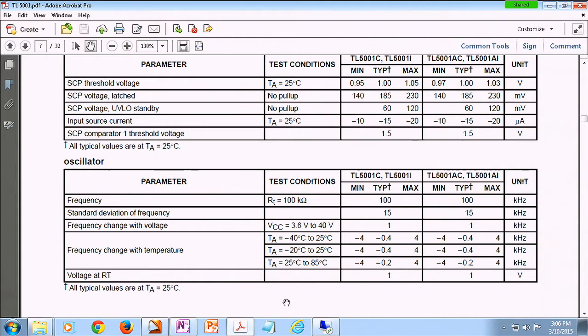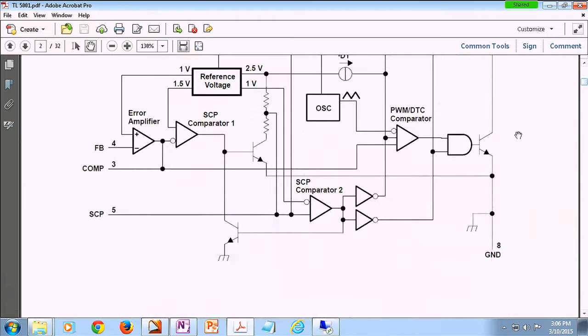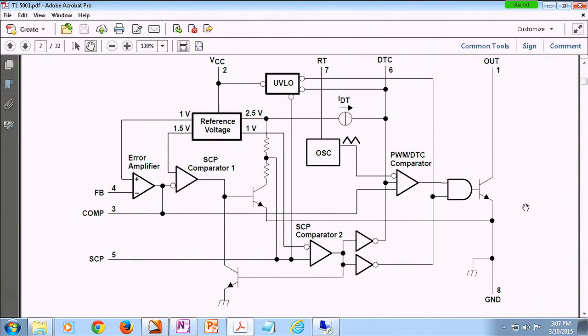Then they have more information about how much current you can sink or source on the output side. If you're, for instance, processing 1 or 2 watts of power using your boost converter, you may say, I'm just going to use this switch as the transistor in my boost. If not, then this could be the transistor of your gate driver. If not, you can just actually use this to feed a gate driver. I mean, it depends on how much current you're going to sink or source.